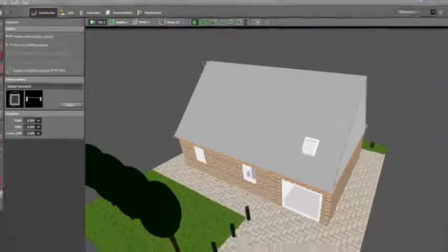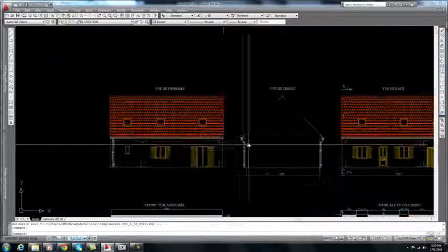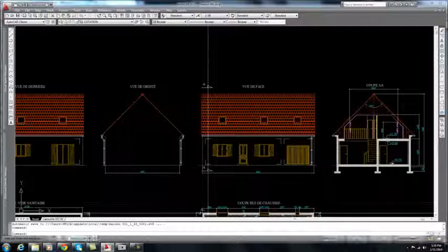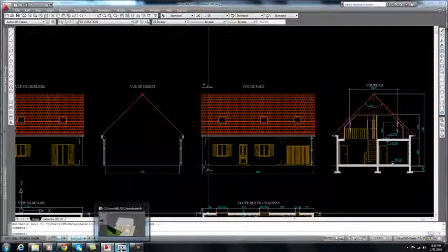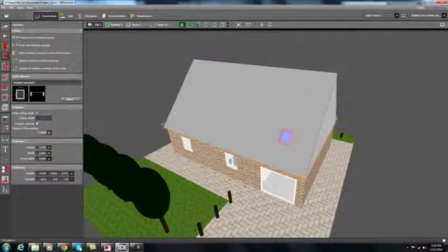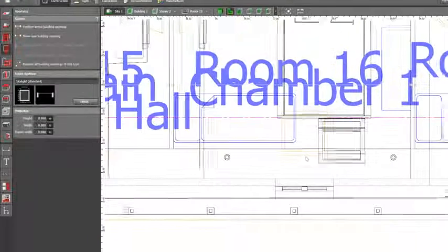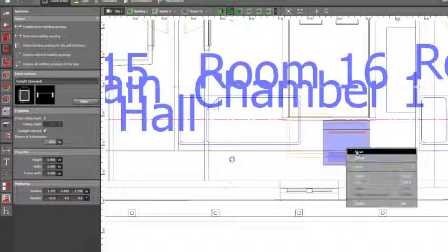And of course, in the CAD file, you will see that there are 3 windows and another 3 windows on the other side. So we have 6 windows or 6 skylights on the roof. So we need to create that one. And since you have this one and you have the size here, you just have to copy it together on the other side and on this side also. So just click this one and then click. And another one here. And then if you want to make sure that the location is correct, go to the plan view, select the window and move it.